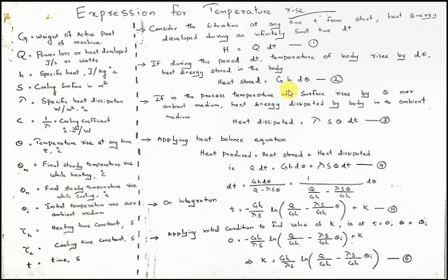As far as electrical machines are concerned, or as far as the expression of temperature rise is concerned, we are considering a situation in which the majority of the heat transfer from the surface to the ambient medium, which we can also call heat dissipation, takes place by convection. So we don't have to consider radiation and conduction. We just have to bother only about the heat dissipation by convection, so we will be obtaining the expression for heat dissipation by convection here.